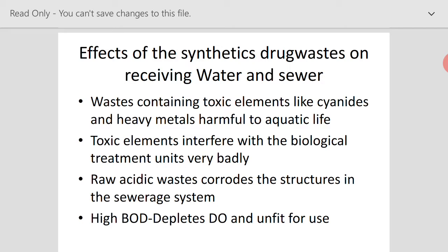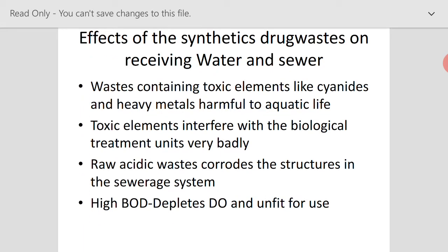So in the case of synthetic drugs, unlike antibiotic drugs, we will have a wide variety of toxic elements like cyanides as well as heavy metals, which are harmful to aquatic life. And these toxic elements will further interfere with the biological treatment units also. The raw acidic waste discharged from such synthetic drug plants will corrode the structures in the sewerage system when it is disposed of into the municipal sewage treatment plant.